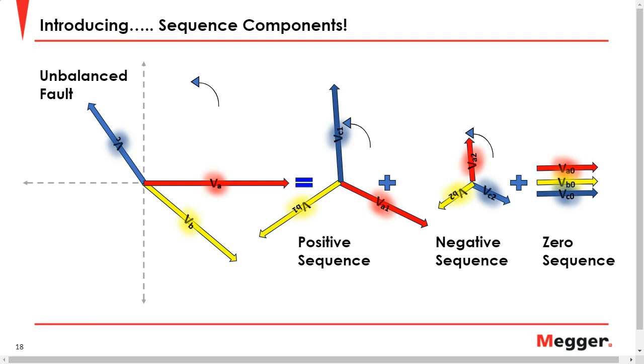So for the triple harmonics, when you have a phase angle of, for example, 120 for phase B, that means 3 times 120, that's 360, which puts the phase B harmonic in phase with the phase A harmonic, because 360 is the same as 0. The same goes for phase C, because in phase C you have 3 times 240. That's actually 2 times 360, so it's just 2 turns, and again, you are on the same phase angle as phase A.